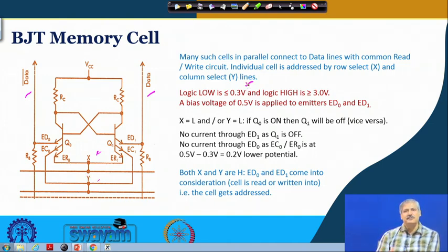And logic high we have seen before, if it is a TTL-based circuit or this transistor operation. So we can consider this to be greater than 3 volt when it is logic high. Other than that, we take note that these lines have a bias voltage connected through a power supply and a resistance. We shall see that circuit a little later, for which 0.5 volt is presented over here. Depending on the amount of current flowing, a small drop might be there, but otherwise it is 0.5 volt.